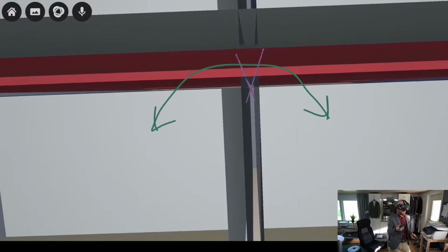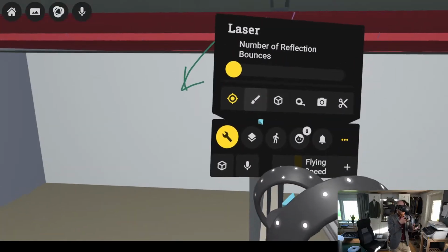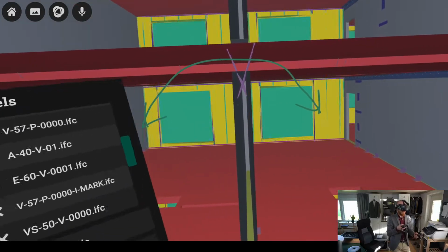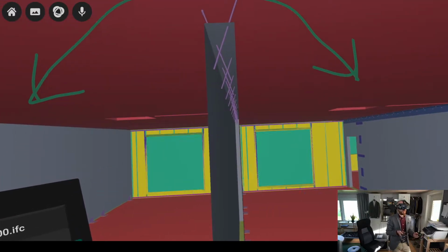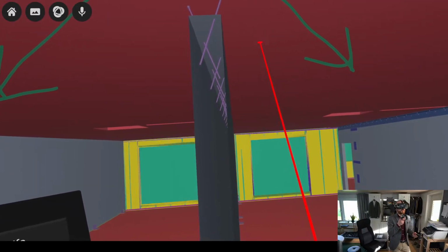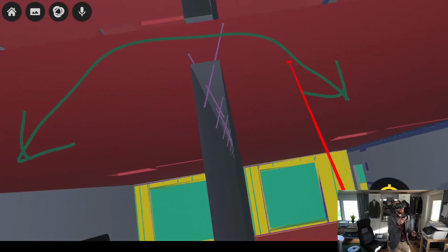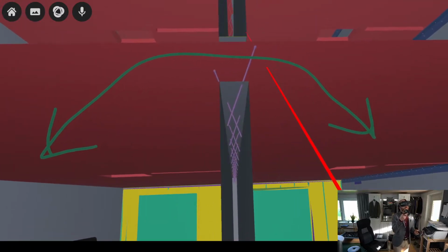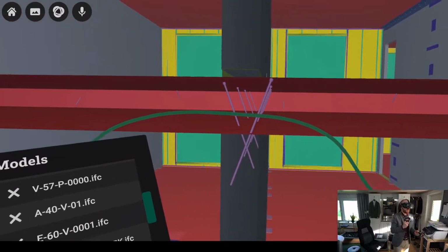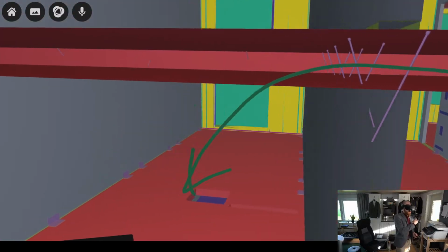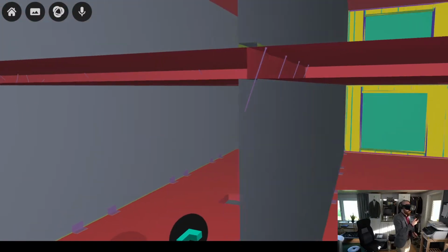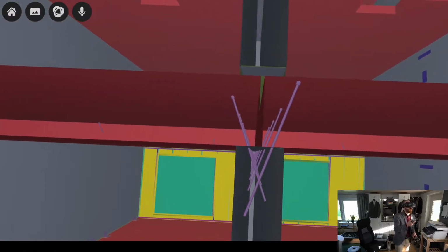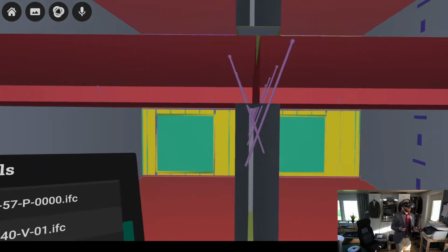So, if you want to get rid of the suspended ceiling, it could be an architectural and aesthetic choice that you might want to have visible wood. Maybe you want to see the wooden texture here in the ceiling. Then you cannot do this at all. If you want visible wood, you have to take this route instead and slice them between every apartment, which has other consequences that you have to take into account.